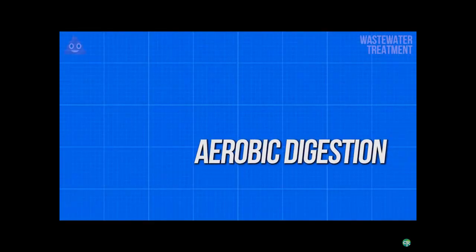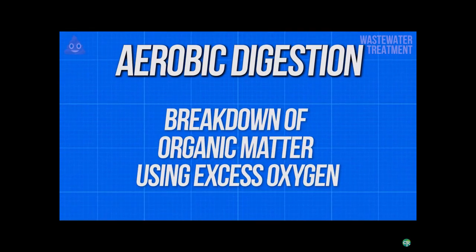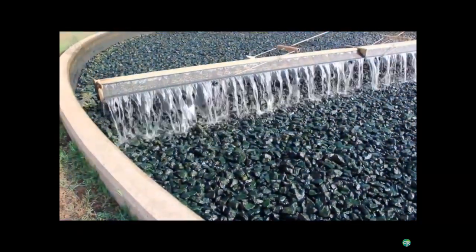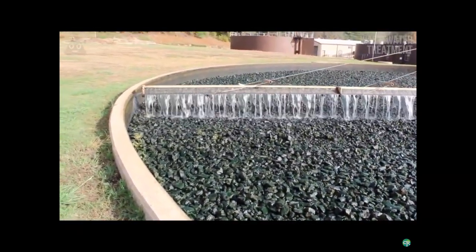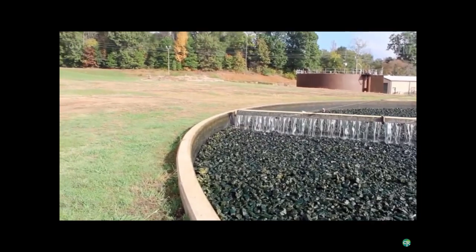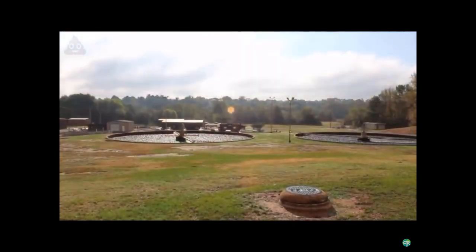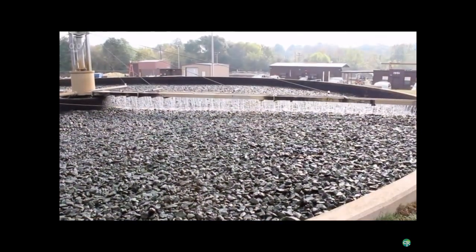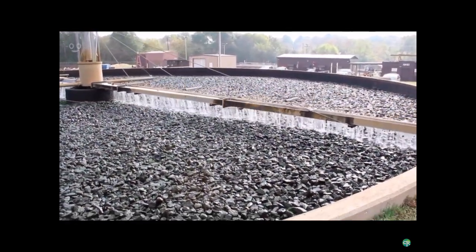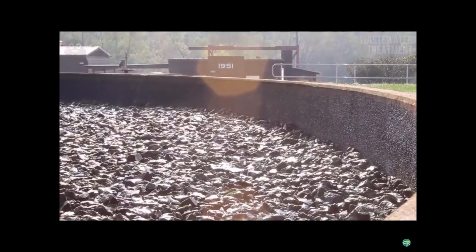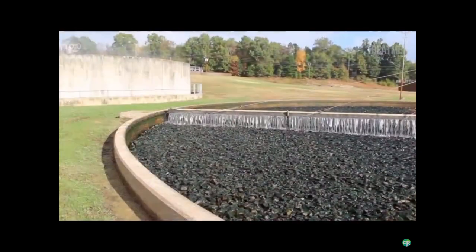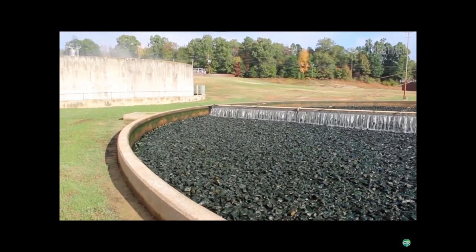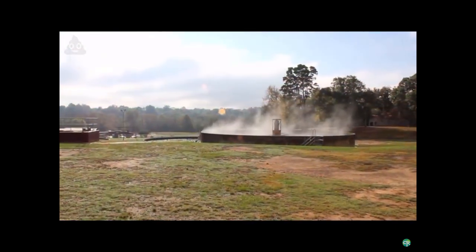Some older plants will add in another step before the aeration basins, referred to as biofilters or trickling filters. Found in many older plants, these filters essentially trickle the effluent over a medium like stone or plastic and allow for a film of bacteria to chow down on any organic matter in the water. This step is largely not used in newer plants due to more efficient and effective modern processes. But for plants with basins already installed, many still use them because they only benefit the treatment process in most cases.